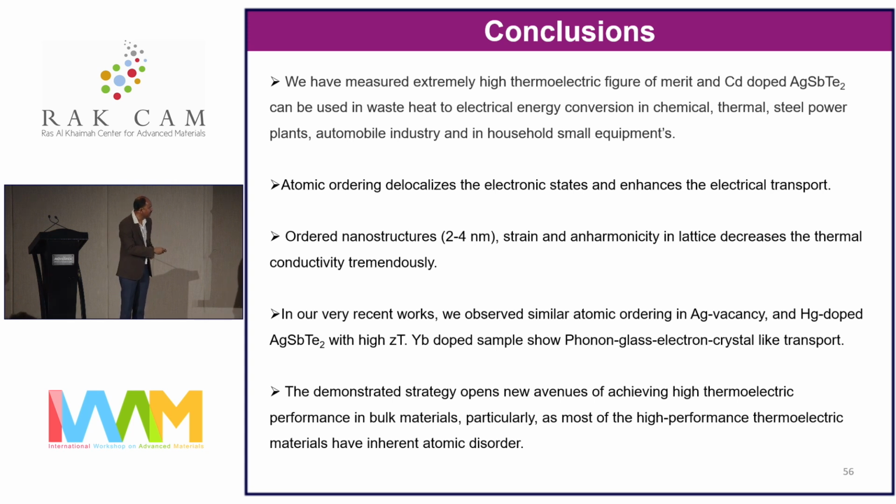And while doing this, I want to tell one general thing. In the thermoelectric community, people thought till now they would solve the problem by disordering the atoms, because there is a significant amount of disorder in all the optimized thermoelectric materials. So we actually went in the other direction and said, okay, disordering is good, but not that good. If we can put in a little bit of ordering, that can actually solve many problems. We can tune electrical transport and phonon transport together if we can create partial ordering in the states. So our idea is general, we believe, and it can be applied to many thermoelectric materials.